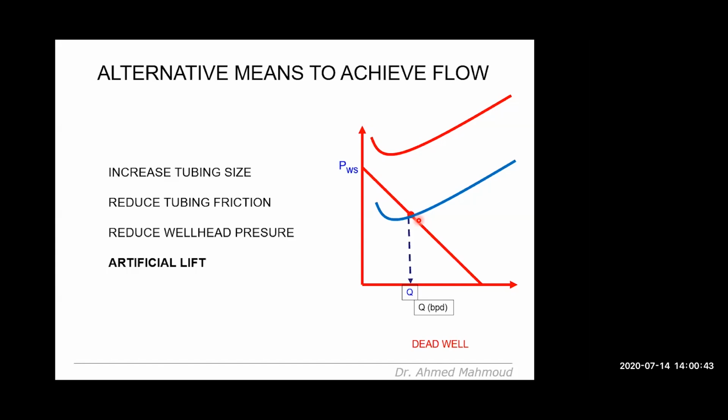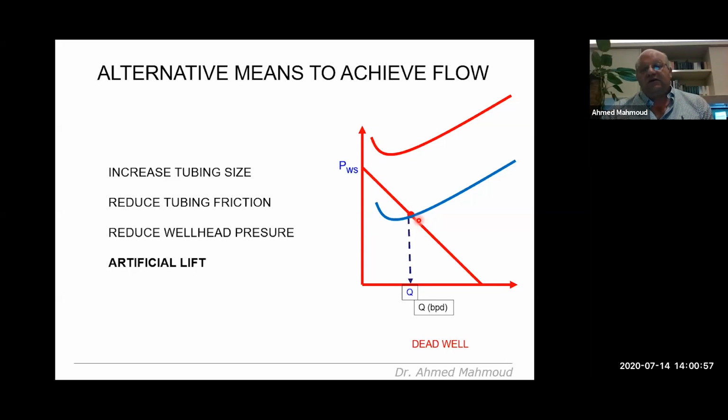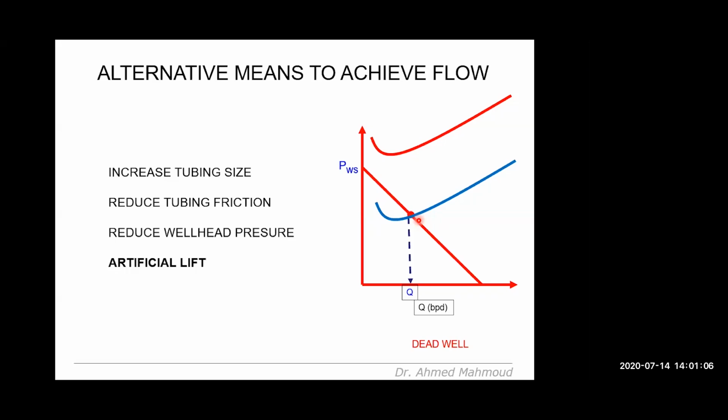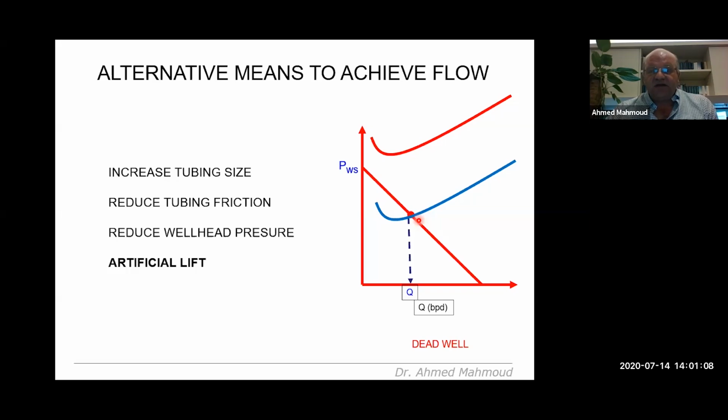The last question. Someone is asking, is that possible to use more than 3 valves in gas lift method? And where is the location of the gas lift valves between tubing joints or in the surface of tubing? Okay, so for the first part of this question, yes, in my examples, I just stayed with 3 valves just to use a simplified example for the purpose of this introductory webinar of gas lift. But obviously, in real life, you can have 5, you can have 7, and you can go definitely more than 3. Okay, it is actually related to the depth of the well.